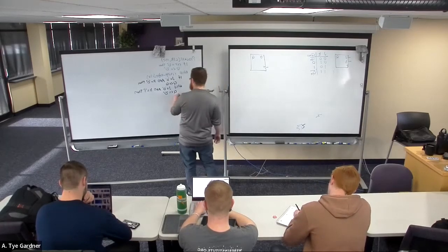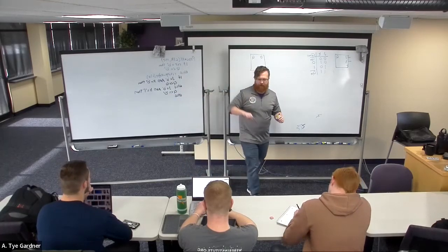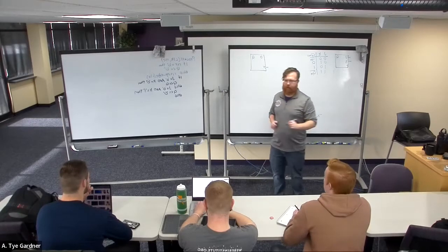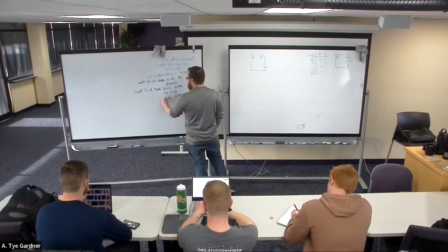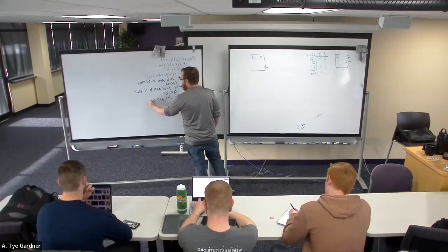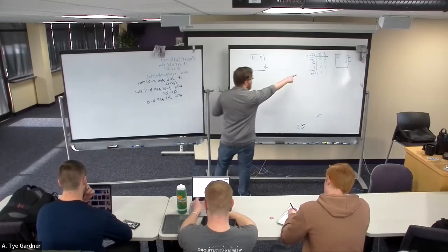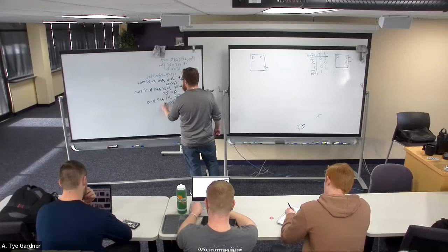Otherwise, right, else if, remembering that there's no space or E in the middle of that else if, which is obnoxious, but it's just the way VHDL is. If J equals 1 and K equals 0, so now we're at the 1, 0 line, Q is 1.